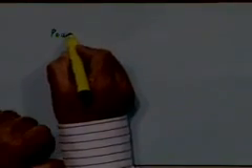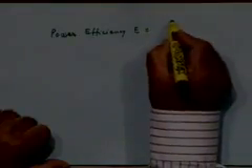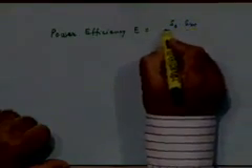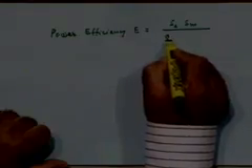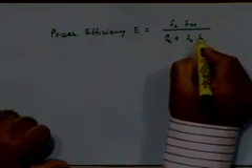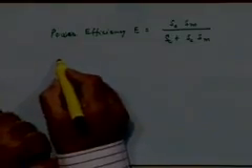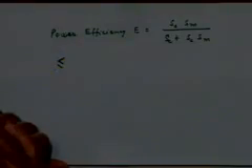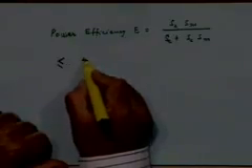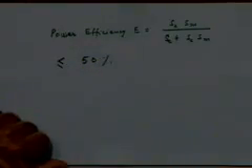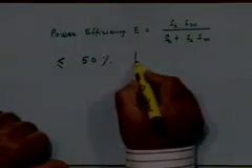Since the carrier conveys no useful information about the message, we can define this factor, power efficiency, call it eta or whatever notation you like, which is this product divided by S sub C plus S sub C into S sub M. Typically this value will be less than 50% for any message signal.